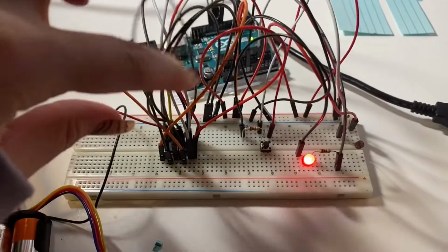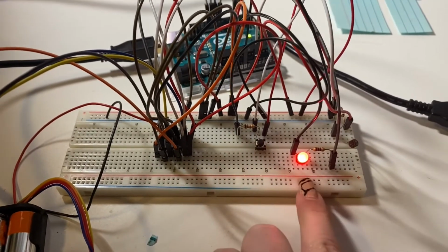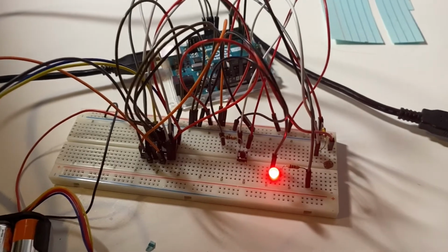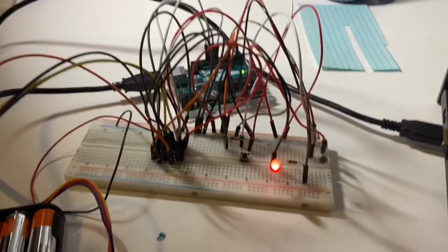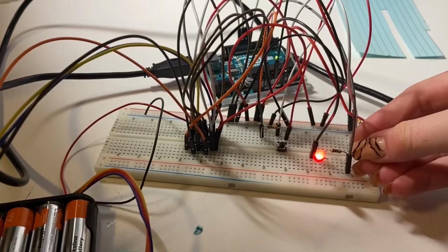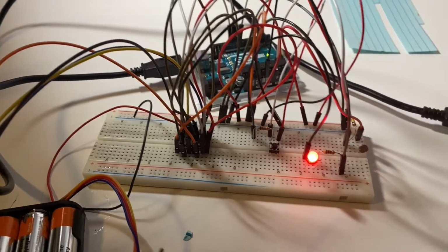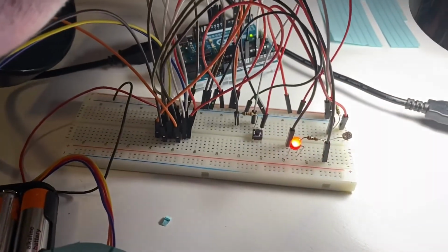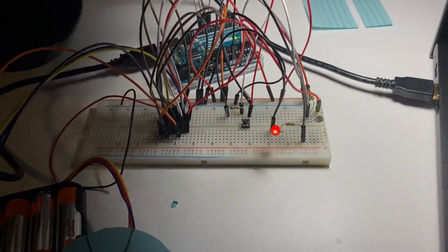So here's my circuit. You have the H bridge over here, and then we have the button right here connected to a resistor, the LED connected to a resistor, and then the photocell also connected to a resistor. So my room is about a medium brightness right now, so the light is a little bit bright. But if I were to cover the photocell as if it were in a dark room, the light would become brighter. But if I were to shine a bright light on the photocell, then the LED light would become much dimmer, as seen right there.